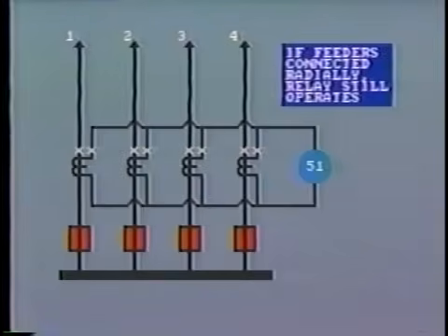For this protection to operate successfully, it is essential that the CTs all have identical characteristics so that the primary currents are accurately represented in the secondaries. In practice, this accuracy is difficult to achieve, especially where the measured currents are of greatly different values.